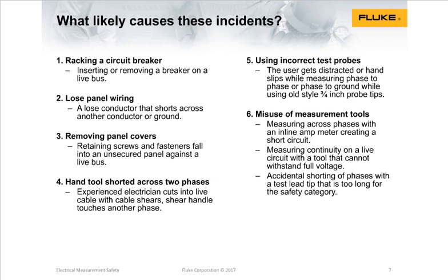And again, it's a direct measurement, a surface measurement of temperature. But if you detect excessive temperature, don't open the panel. Go downstream, shut off the lockout, tagout, shut off that panel before opening it, because there's a strong likelihood that there is a degree of arcing or overheating taking place.